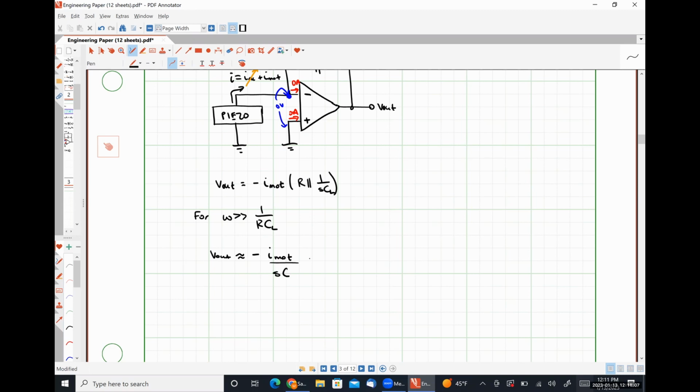Since our motional current is also dependent on frequency, we're going to have negative s e A times our strain, where I'm intentionally not putting in my subscripts here because I want it to be applicable for everything. So I don't want it just in a 1 direction or just in a 3 direction. E, lowercase e here, is whatever piezoelectric coefficient we need. A is the area of our plate.